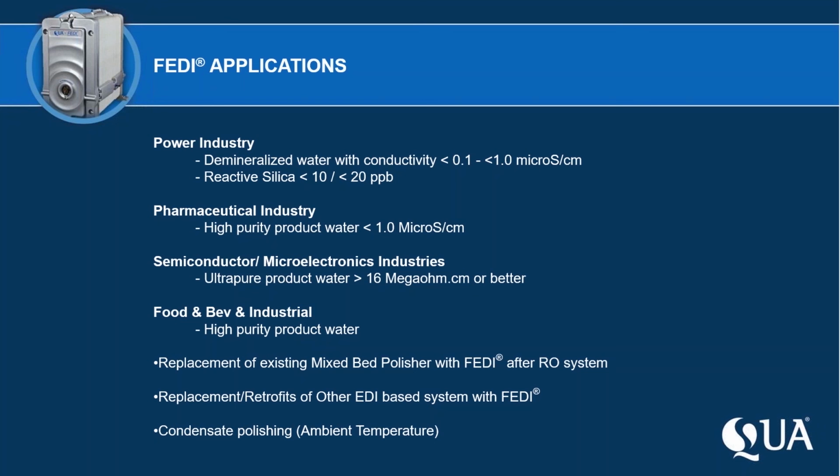We'll look at the pharmaceutical industry, and I'll have to say EDI was first accepted in the pharmaceutical industry. And I'll have to say that Millipore was probably the first to commercially introduce it. When it goes into the pharmaceutical industry, the beauty about the EDI or Fedi technology is it's not so much the water product quality it can make, because we're only looking for, say, 1 microsiemen, though the water that it produces is well over 5 and approaches that 18 megohm holy grail type of water.